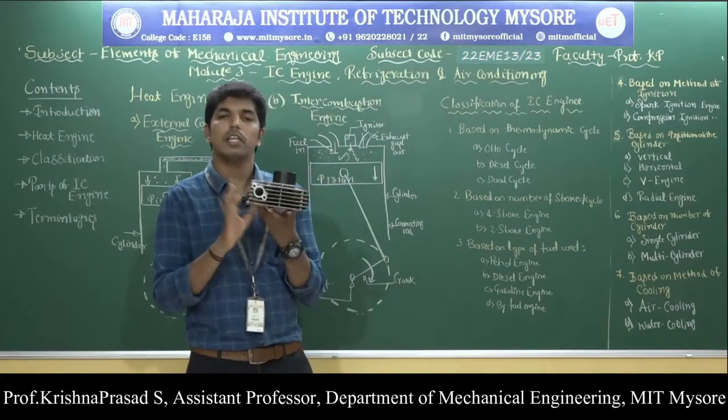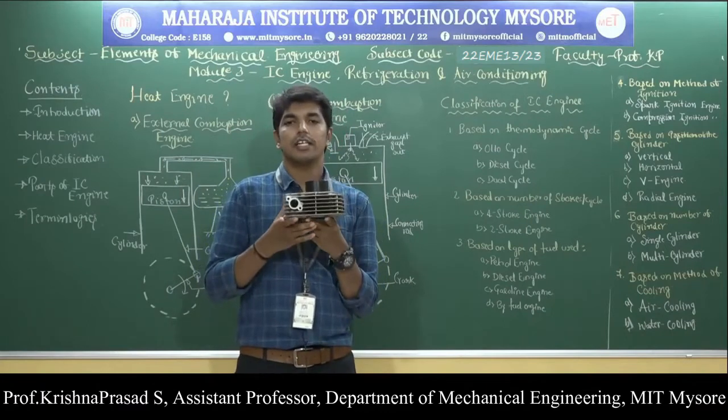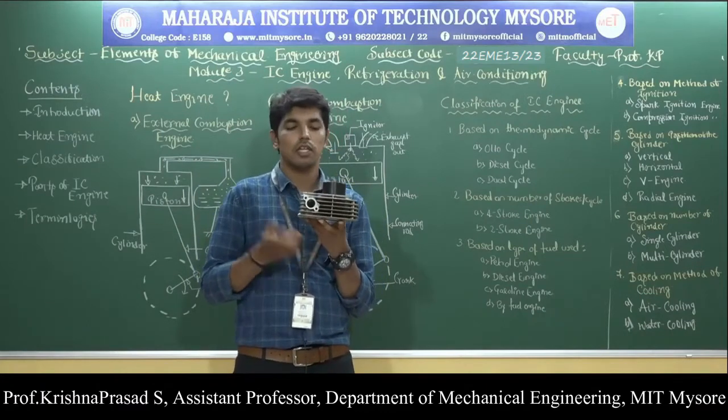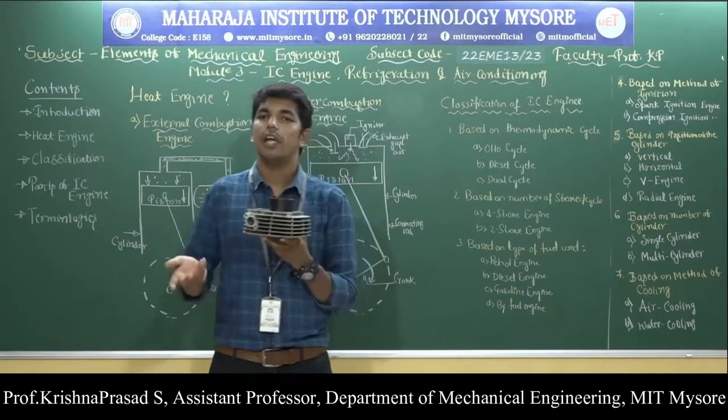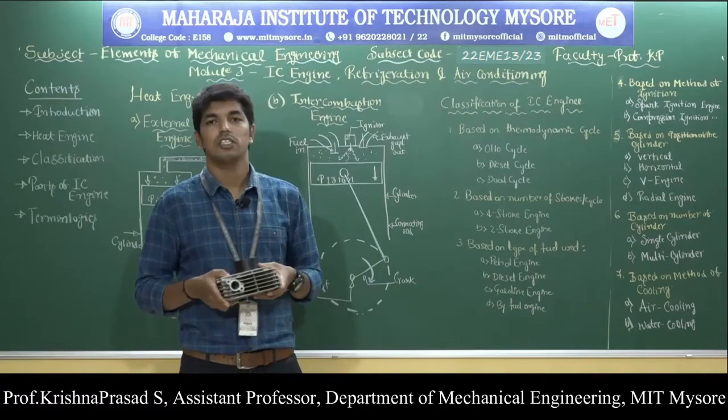So this can be done with the help of the fins. The fins increase the surface contact area with respect to the atmosphere, so that heat can be easily dissipated into the atmosphere. Air cooling systems are generally used where scarcity of water occurs.